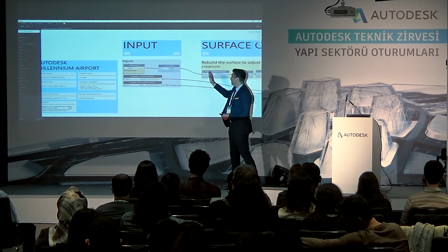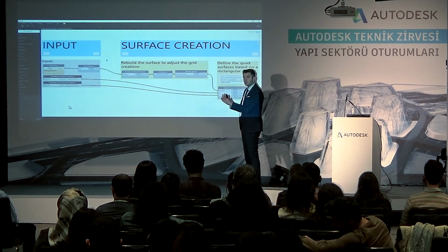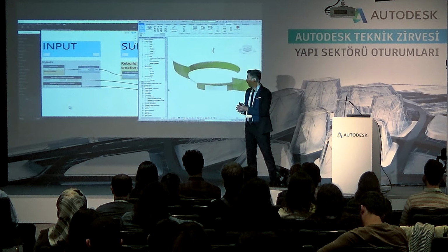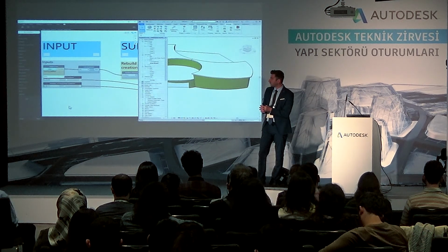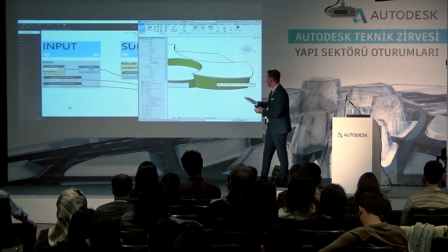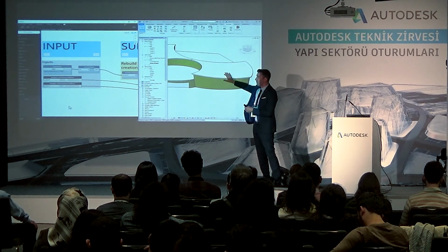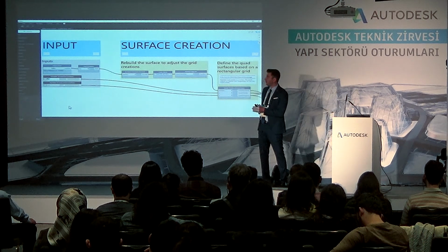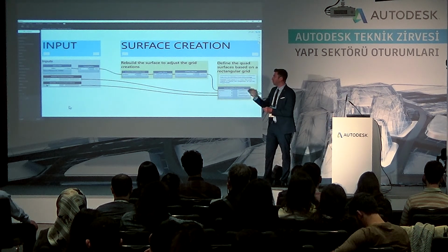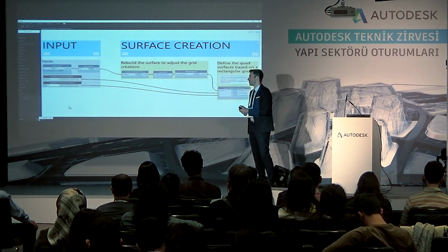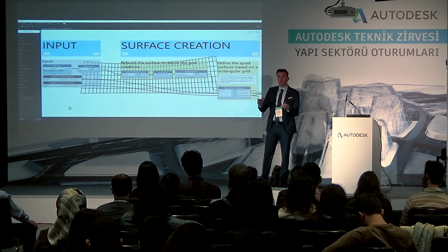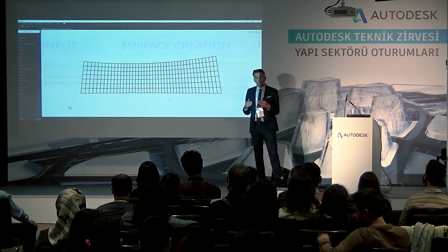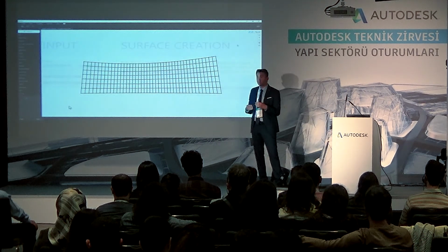Of course, everything can be organized into groups of nodes, so we can easily debug the nodes. First step is to read the facade. After we brought the mass geometry from Formit inside Revit, we can read the facade, bring it inside Dynamo for processing. And we can reutilize the same nodes, the same script that we used in the concept phase. We will just have to improve it.